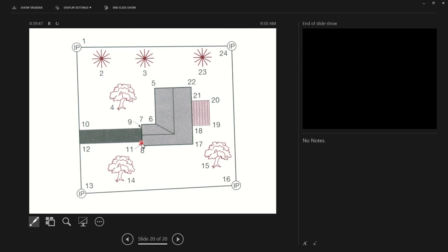If we just say straight up SW, it's going to draw a line like this and then a zinger back to 11. So 11 is an SW space B, 12 will be an SW. 13 will be an IP, space 1 for the size of the pipe is 1 inch. If it's not, you can just put IP. Number 14 is a deciduous tree, DTRE. 15, deciduous tree, DTRE. 16, IP, for an iron pipe. 17 is that building code again. Look at that, we went from 8 all the way to 17 for building. So this would be BLDG.